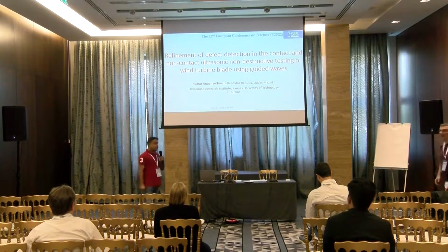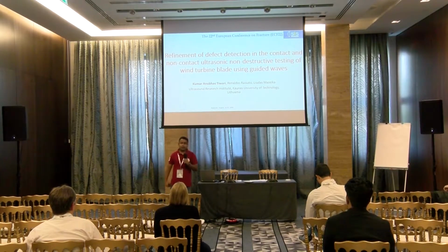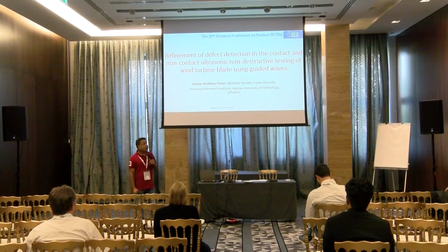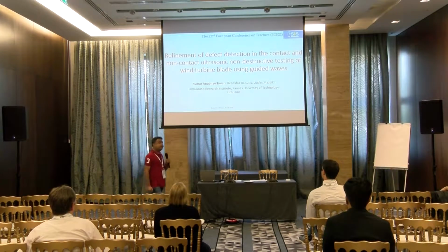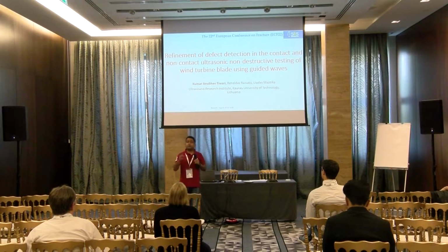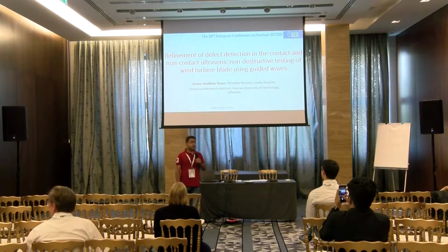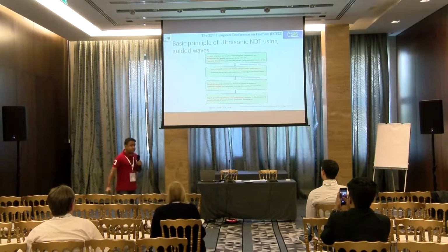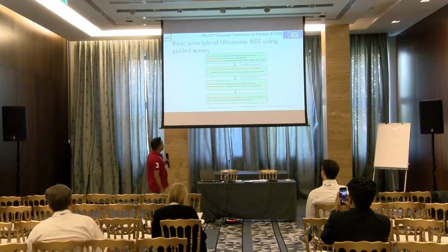Very good morning, Honorable Chair and the researchers. My name is Kumar and I work at the Ultrasound Research Institute of Kaunas University of Technology, Lithuania. I am here to talk on refinement of defect detection in the contact and non-contact ultrasonic non-destructive testing of wind turbine blade using guided waves. So what are guided waves? Guided waves are ultrasound waves which travel over the thickness of the structure depending on the excitation frequency of the transmitting transducer. This is the basic principle of ultrasonic NDT using guided waves.